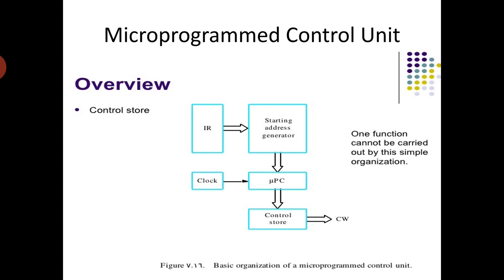In addition to the branch address, these micro instructions specify which of the external inputs, condition codes, or possibly bits of the instruction register should be checked as a condition for branching to take place.